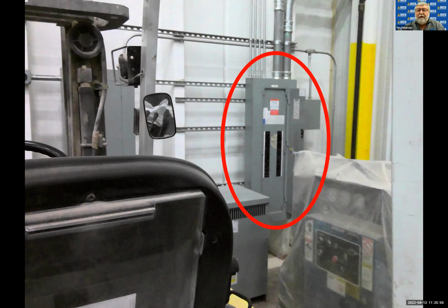If it says power panel L1 breakers 2 and 4 run my grinder, and it's been rewired and it doesn't run my grinder, it could create a lot of problems. So double check your power panels, make sure that they're labeled. Every breaker, and if it doesn't control anything, write down on it, blank, not in use. Those are the things that are important.